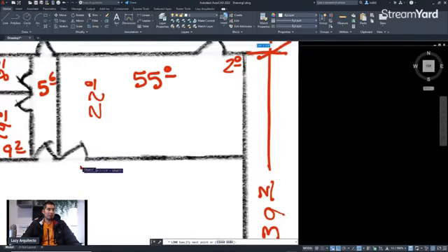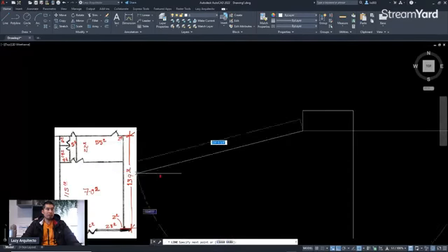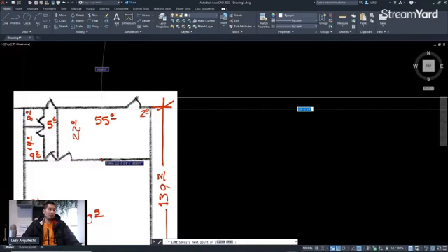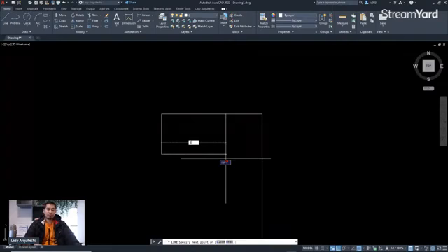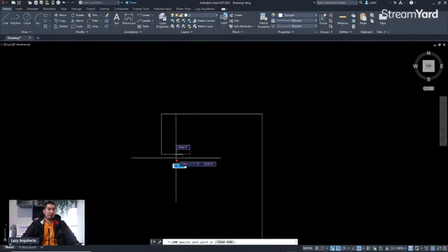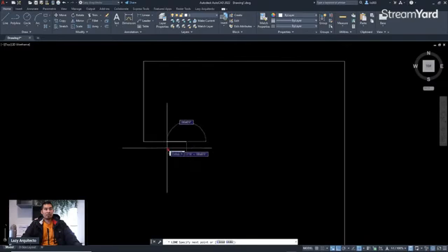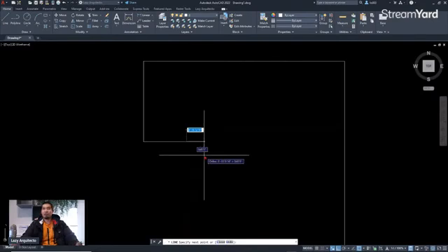And then, of course, I need to close this room. So there's no dimension here. Why? Because this is a rectangular room. And of course, it's going to be 55 feet also on the other side. So at this point, I can type 55 feet, or I'm going to cancel that because, oops, I made a mistake here, right? Let's say I draw a line that I wasn't supposed to draw, this short line. So what do I do in this case? I simply can use the Control Z shortcut to undo my mistake.